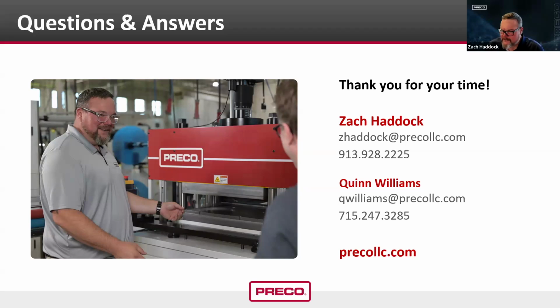The other side of that, and you need to be careful with it, is if you've got a press that is capable of dwell, you need to make sure that it's capable of an active dwell if you're going to try to do that. Because if it's not an active dwell, meaning that it's holding that tonnage down, it's essentially just coming down, then bleeding off all the pressure anyway. So in general, no. Are there some extenuating circumstances? Yes.